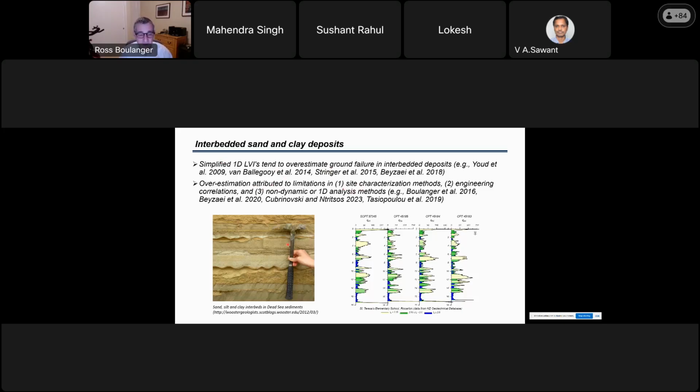The first reason is site characterization, and you illustrate that with this photo. If you have interbedded sand, silt, and clay interbeds, and they are on the order of just 10 centimeters thick or something like that, well, when you drive a CPT through this material, or you drive an SPT through these materials, the failure mechanism, the tip resistance, engages a volume of soil that is larger than the interbeds. So the tool never measures the property of any one interbed, but rather a composite smearing of their properties. And that means you never get a good result for any of the materials. And so that's a challenge.